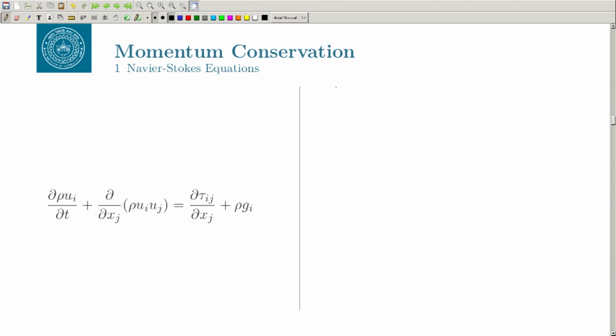If you use B equal to mV, you get b equal to V, and you can derive an expression which will be similar to the mass conservation, but will have more forces or more stress terms in your momentum conservation. That will give you rho u_i by dt. Why i here? Because momentum is a vector quantity, so you can derive it for individual directions i, j and k. Mass and energy are scalar quantities, so you will have just one equation.